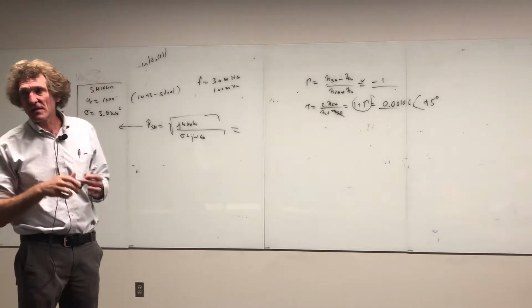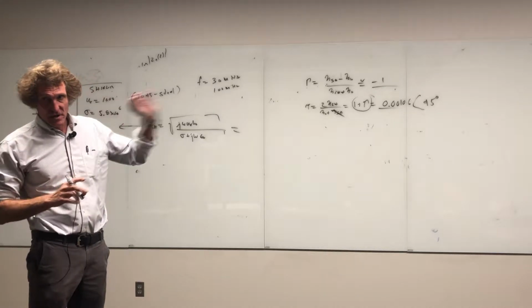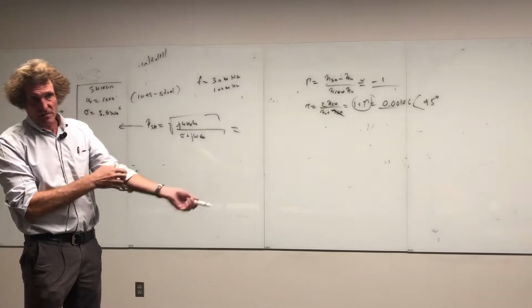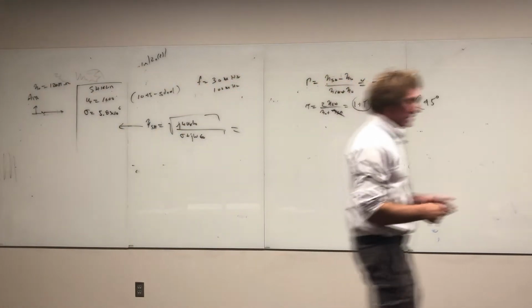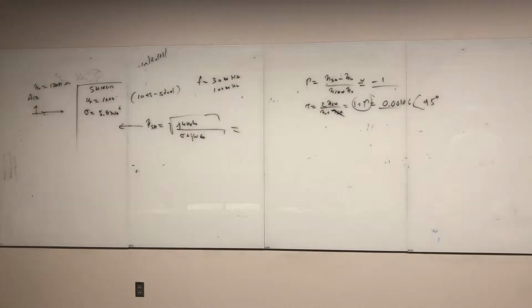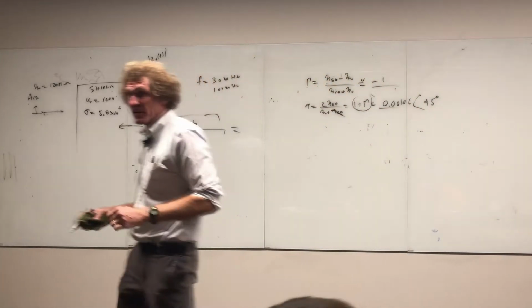So make sure if you're at high frequency and for whatever reason you have to deal with this kind of shielding effect with steel, that you get the values at the frequency of operation. Don't look at just generic values. It's the same with epsilon relative, because in water they say it's 81. Well, it's 81 at a certain frequency range, not at very high frequencies.